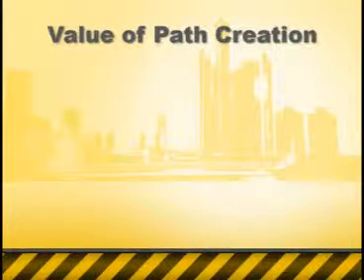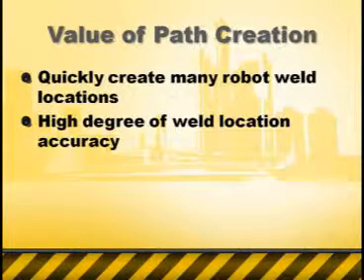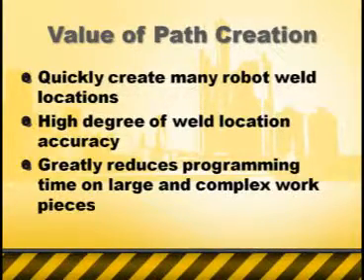So let's talk about the benefits of what we've seen. The system's capable of creating a lot of robot locations very quickly. Imagine that a programmer is working on a part that's extremely large like this one. Using the teach pendant takes an exorbitant amount of time to create all those robot locations, especially if it's a very complex part where you can't copy or mirror the locations. The simulation with offline programming allows you to quickly create hundreds of robot locations and create them more accurately than you could with a teach pendant.